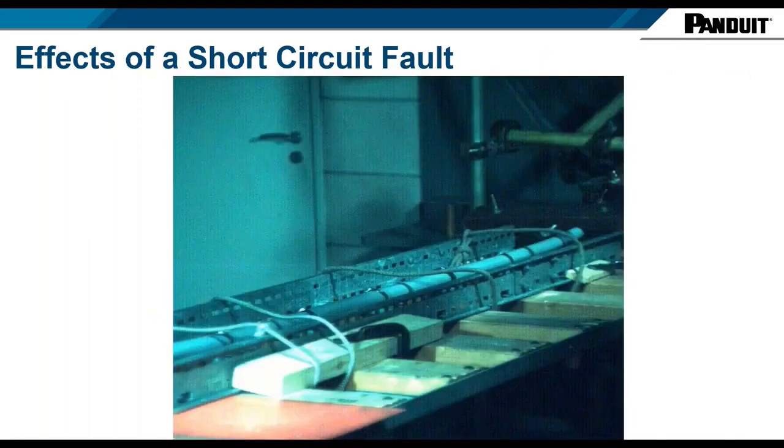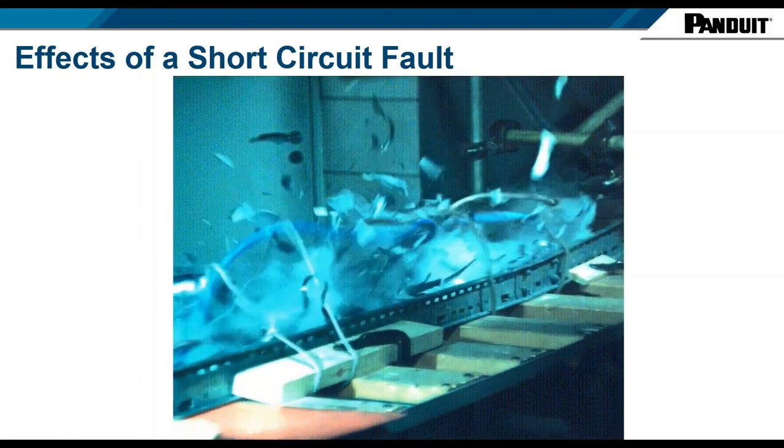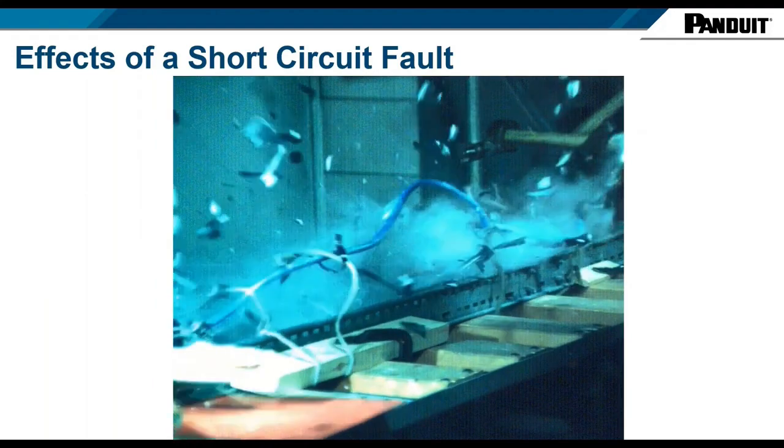So this here is a multi-core cable. It's an unarmored multi-core cable, but we get the same effect with a steel wire armored or aluminium wire armored cable, albeit to a lesser effect, but we still see the same effect on an armored cable. Again, at the right-hand end, we've got connection to generation. Left-hand end just out of shot, a copper busbar to induce the short circuit. This was a 3-core 95 tested to the installation level given. When we carried out the short circuit test, this is the effect of a short circuit on a multi-core cable.